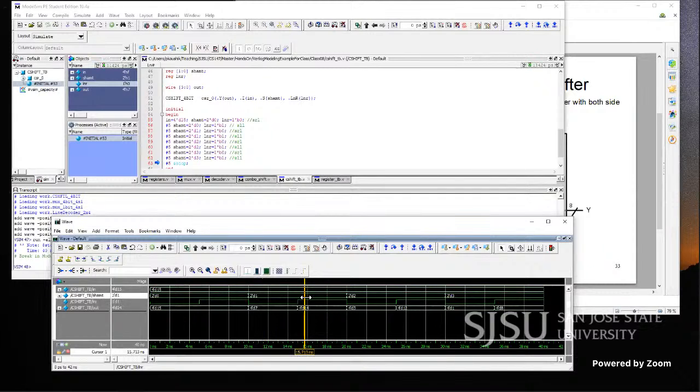But if you do it the other way, left shift, then the LSB will become 0, everything else is 1, so that means 14. So 7, 14 comes out here. With a 2-bit shift, similar logic: right shift would result in 3, left shift would result in 12, and with 3-bit shifting, right shift would result in 1, and left shift would result in 8.